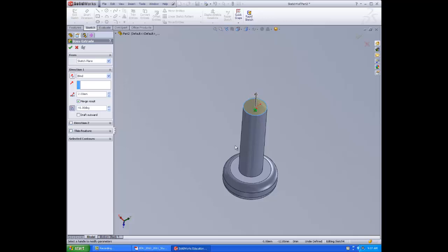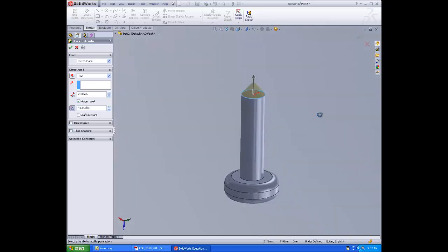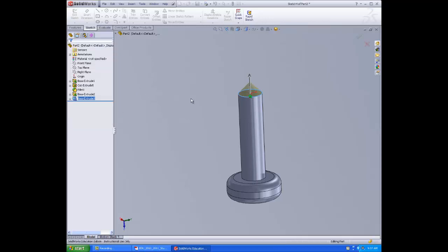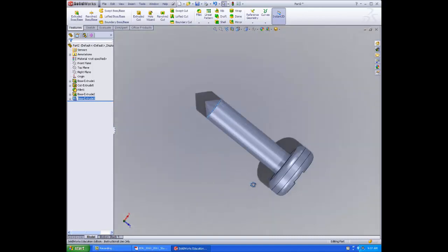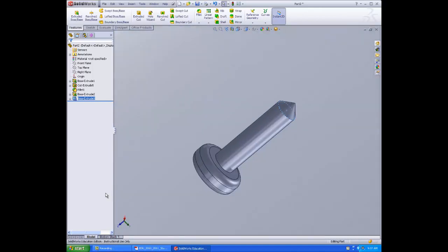And we're going to set it so it actually comes to a point. And that, for us, is at 45 degrees. And click OK. And there you go. You've got an edge. Now you may notice we're not gonna actually make the rivet, and that's because usually for this we just use a simplified form.